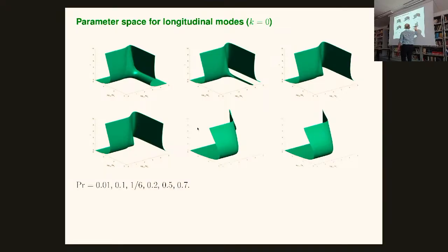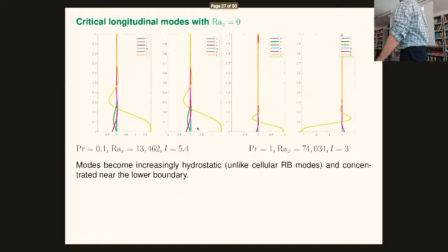And then for large Prandtl number, and by the way, this is 0.7, so this is air. All this zoo of good stuff is for small Prandtl number, right? So it's completely not relevant for water or cold water, unless this thing here survives but moves away. But at least there's serious questions about what happens in environments where your vertical Rayleigh number is 0 and your horizontal Rayleigh number is large. It's not clear what's going on. Now, I suspect that in any of our real-world applications, the horizontal Rayleigh number is way up here, right? So this is all worrying about nothing, because you're clearly unstable convectively, unless I guess you're freezing your core.